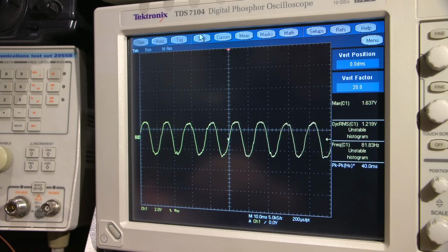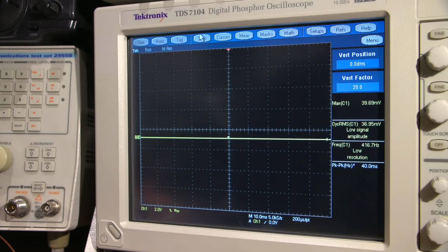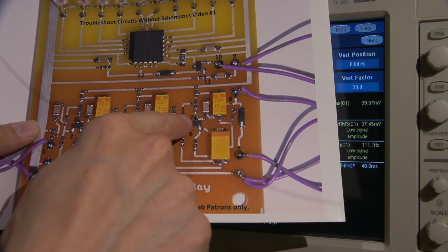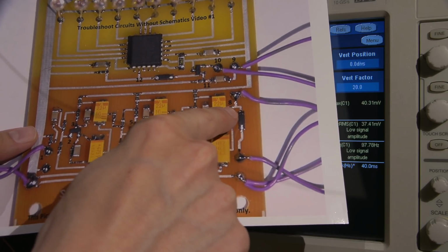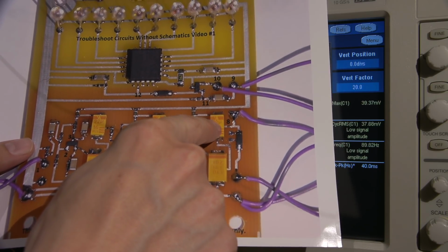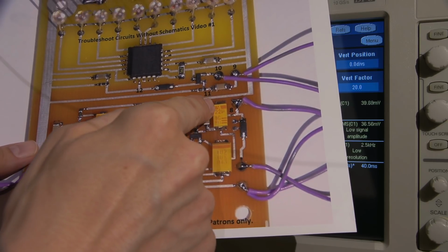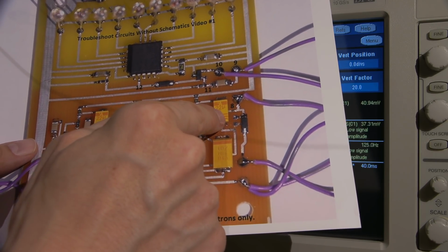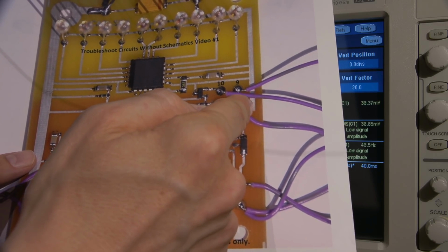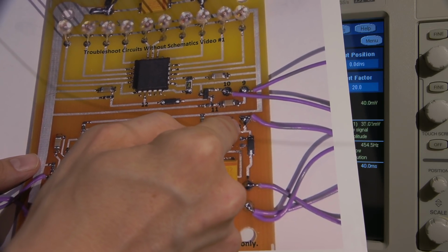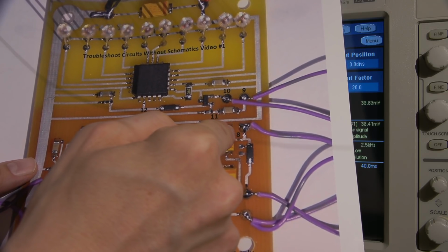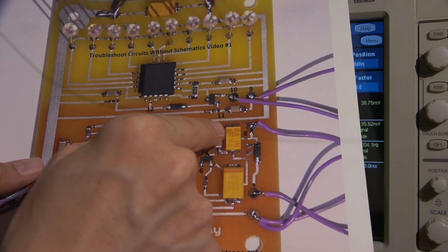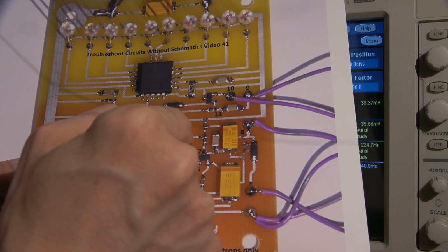So in this case, you can kind of see the same thing. If you look at the schematic, say that last capacitor was an electrolytic capacitor, and you can see how that trace goes directly underneath that cap. A lot of the time flaws hide directly underneath electrolytic capacitors, because right where the leads come out of the seal on the bottom, and even surface mount electrolytic caps, they leak. They put a little puddle underneath, and that over time will just rot right through the trace, and you get an open connection from this side to this side, and they hide.